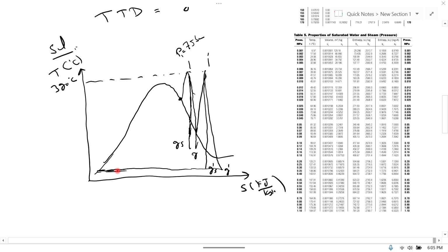This is the condenser, heat rejection in the condenser from 2 to 3. This is point 3. From point 3 to 4, this is the pump work, and then it goes to the boiler. It is heated in the boiler, and steam is generated from point 4 to 1. And here it is again cascaded to the condenser. So this is the TS diagram for the problem.